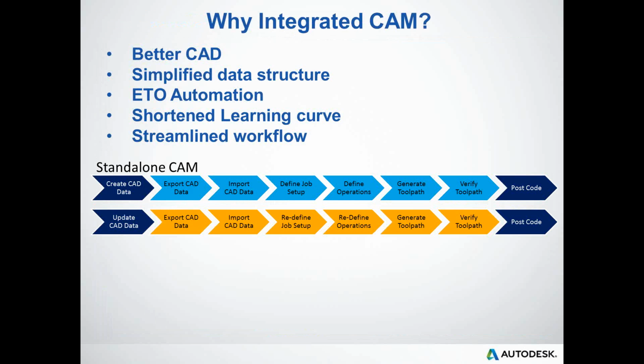If there was a change to the design, you would have to re-export out that CAD data, re-import that CAD data, verify your toolpath, perhaps redefine operations, redefine a setup, and re-verify.